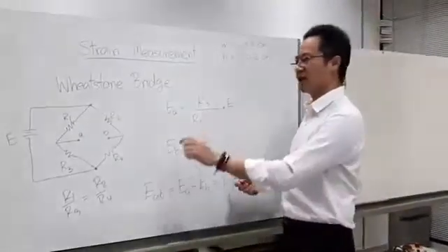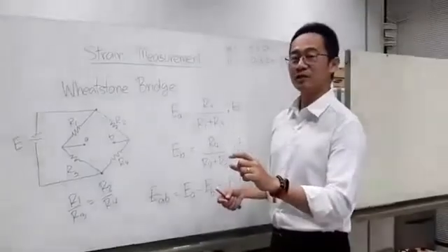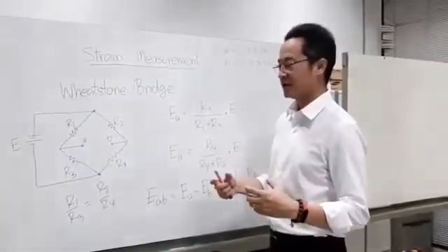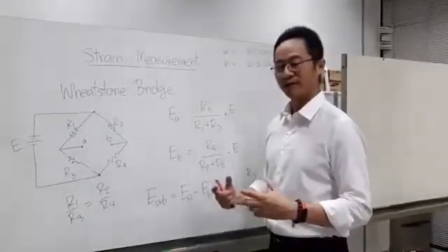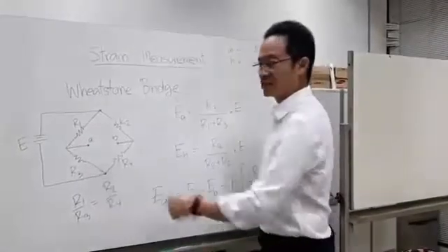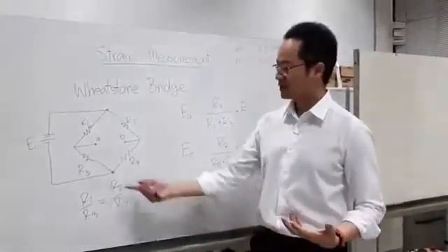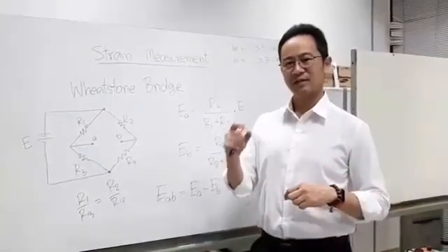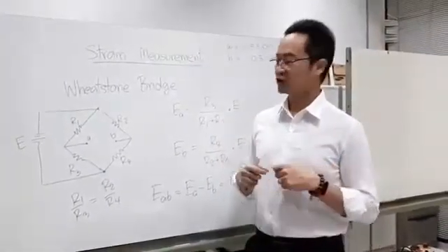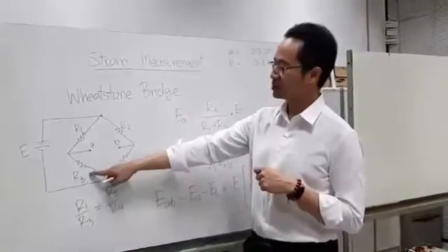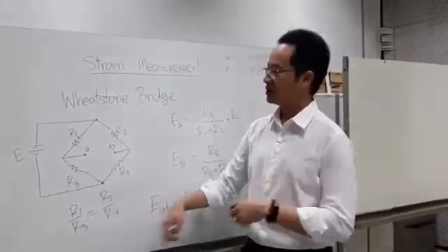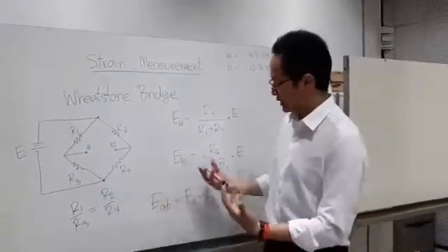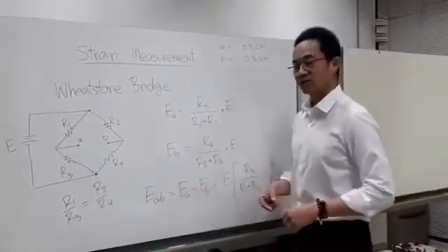If I put the strain gauge to measure the deformation of any system, when it starts deforming, the resistance will change. Why is it changing? Resistance depends on the length and on the diameter of the wire, as you learn in solid mechanics. If this is changed, the ratio is changed and the system is not balanced. Then the output voltage is not 0.